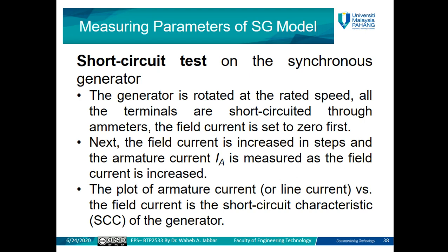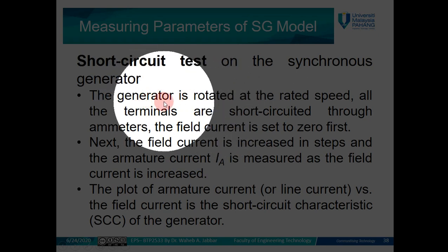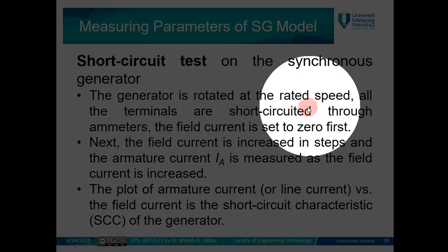The short circuit test for the synchronous generator is conducted by short circuiting the terminals of the generator. The generator is rotated at the rated speed.